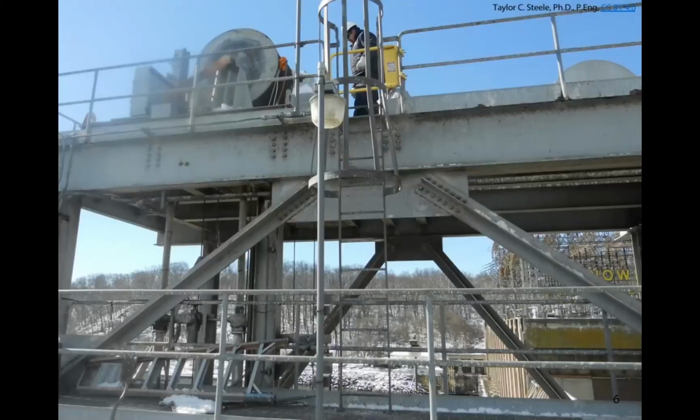From time to time, though, we might use WT sections. It's more common in industrial structures where we don't really care what they look like, and we don't try to bury the braces within any kind of wall finishing. So if they're exposed in an industrial structure, we tend to use these WTs. They're often used as braces, and they're similar to flat bars because more or less the flange here of the WT is basically a flat bar. But then we've got the stem, or what's part of the web in the W section it's cut from, and that helps to provide some nominal buckling resistance. These are commonly used as tension compression braces in structures like this.